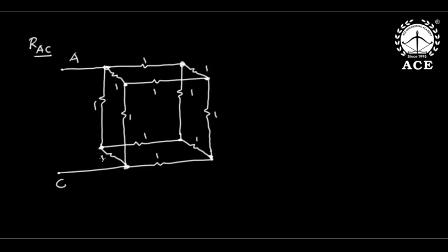First of all, RAC are the opposite diagonal corners of a surface. That is the first thing. Second, if resistors are not equal and you want to do the conventional way, make it planar and do star delta, delta star transformation, then you will get the answer. That is a real challenge. But here let us apply basics.